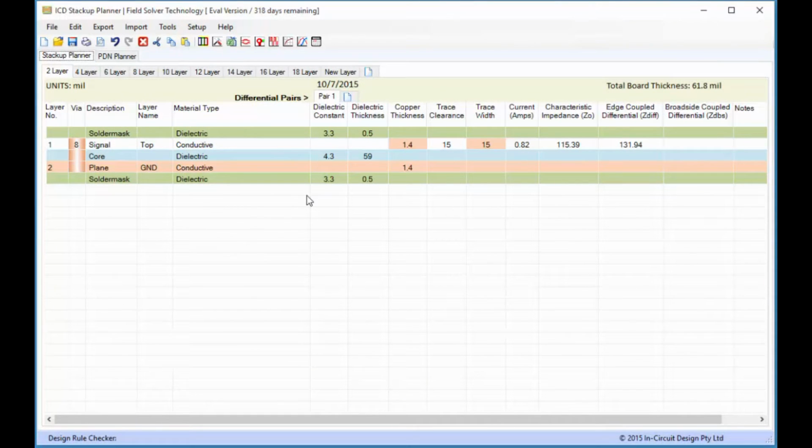All right, and then in addition to it, obviously we have our Stackup over here. Now, impedances are an interesting creature, because impedances are completely reliant upon the board Stackup itself. And as a matter of fact, some people may think that, well, I've still controlled the width of the trace, and I might be able to control the space of the trace on my own. But that's not necessarily true, because if we really think about our Stackup planning, in addition to things like the dielectric constant or the height of the dielectric, or even the trace height or the trace width, we know what the impedance is.